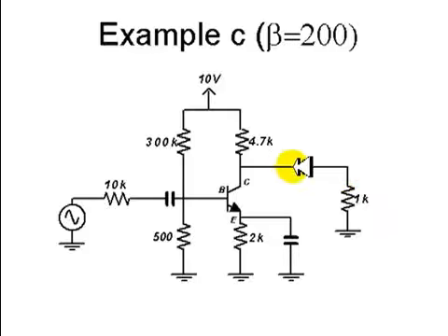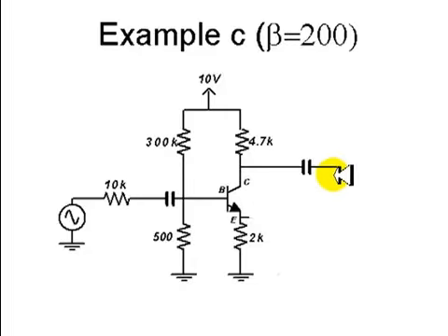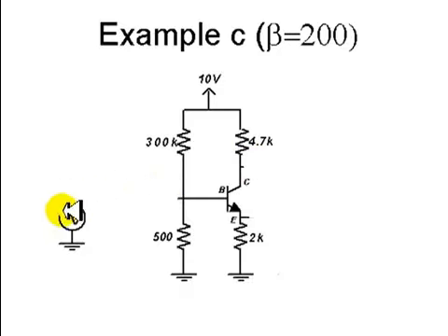We'll eliminate this load resistor and this signal source. This will be open, and this load will also not be there in DC, or the input signal source either. Superposition, remember, we're solving the circuit in DC only. We're solving that in the bias circuit. Let's analyze this one.